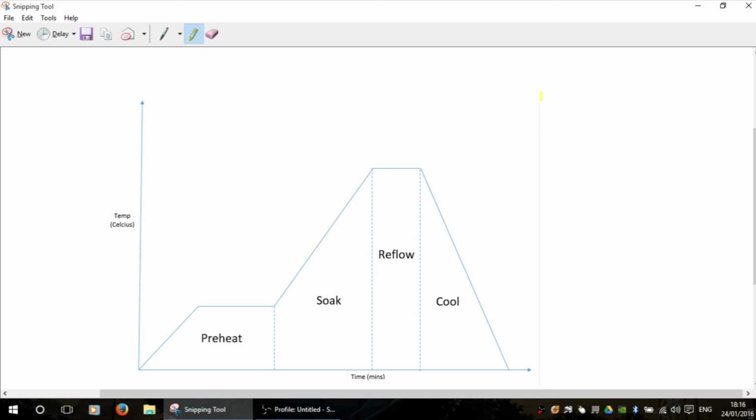So, with that in mind, and again, as I say, different heating plates between batches, you can have two identical machines which run completely differently. And that can also be said for two machines identical in every single way in the same room, but they can both have different profiles for that very reason. So don't assume that just because a profile works for one person that it's going to work for you, because chances are it won't, or you'll at least have to do some tweaking to it to get it to work properly and in a desirable fashion.